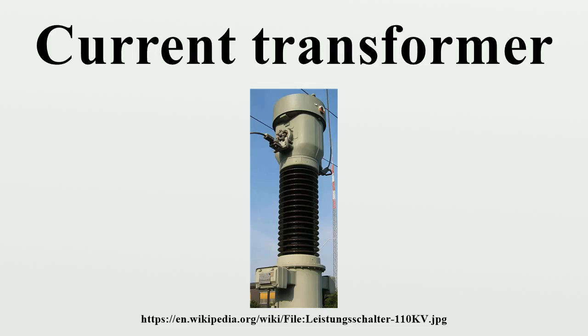The knee point voltage is less applicable for metering current transformers as their accuracy is generally much higher, but constrained within a very small range of the current transformer rating, typically 1.2 to 1.5 times rated current. However, the concept of knee point voltage is very pertinent to protection current transformers, since they are necessarily exposed to fault currents of 20 to 30 times rated current.